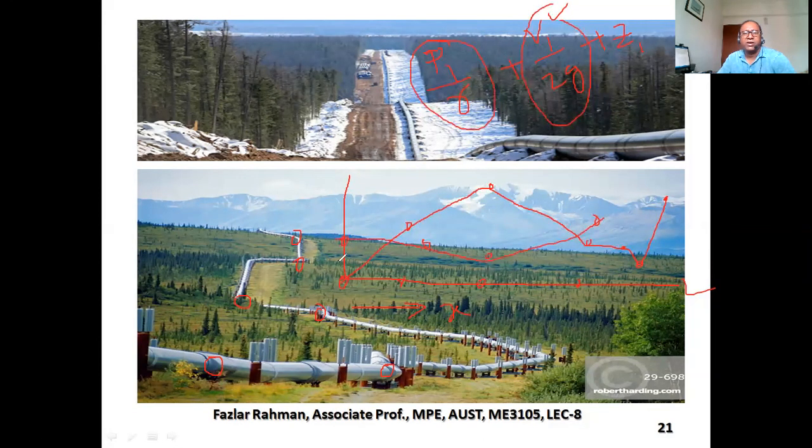You see P by gamma, say right over here is too high, then it is again increasing, then again decreasing, and just show him the graph. So he can observe the pattern of your pipeline from one region to another, where the pressure is too high, where the velocity is too high, where the pressure head is extremely high or extremely low. Okay, so this is the application.